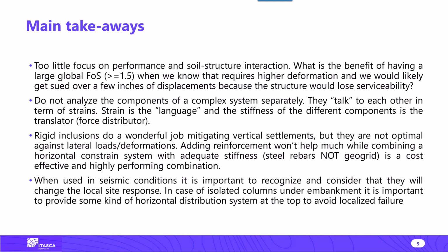Another topic is that when you have a large extension of ground improvement in seismic conditions, it tends to change the local response also. Essentially, you would get a higher acceleration that is brought up into the superstructure when we modify the soil stiffness using this type of improvement.